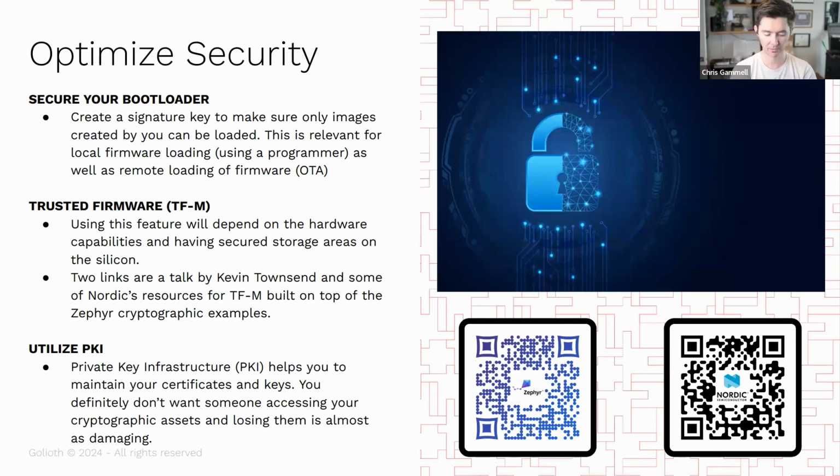And some simple things too, right? Like the default key in the bootloader, you probably shouldn't be using that at any time, even at the 1,000 stage, right? You should already have your own keys in your bootloader for your device, for a couple reasons. One, for general security, making sure that some rando off the street can't send you a firmware image.